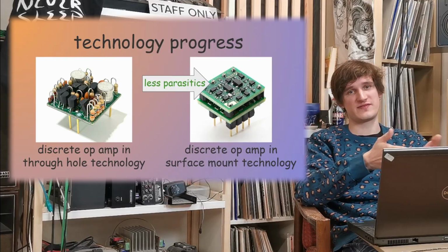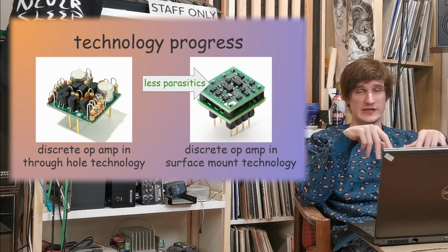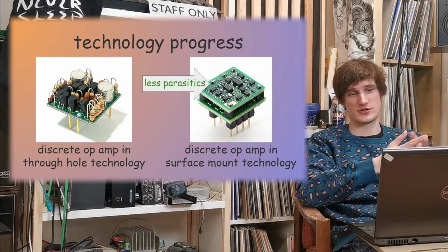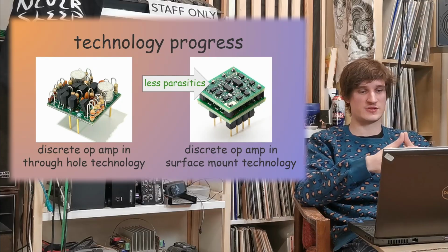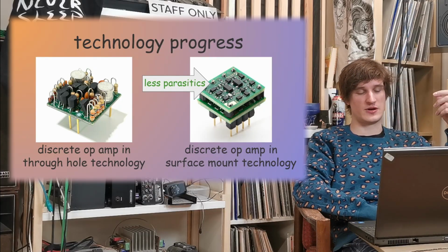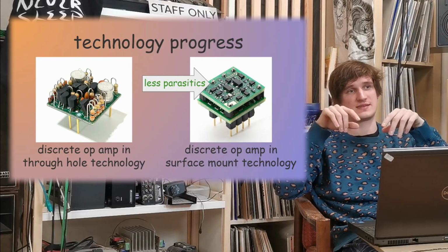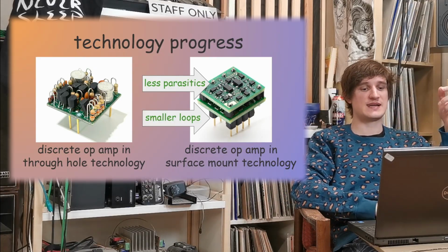But if you want to really dive deeper into it, I recommend just Googling electronic component parasitics or stuff like that. Later on, I will also tell you about a nice book that describes this. And also, what's nice about this SMD technology and making the design more dense and the traces shorter is that the current loops, because current flows in loops, are much smaller, and thanks to the smaller area of the circuit, this circuit is less prone to interference.